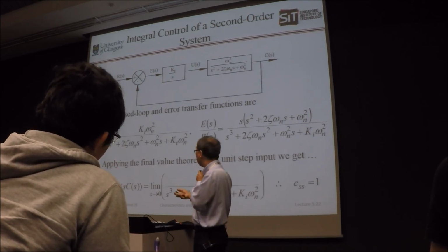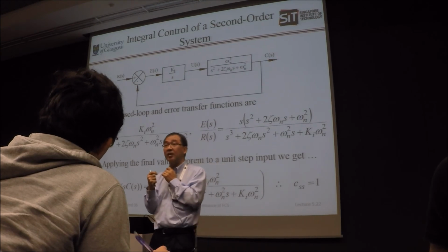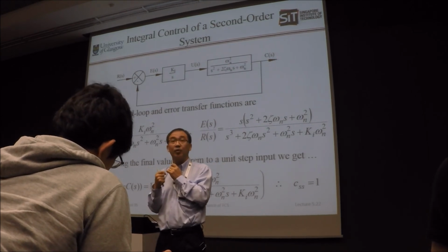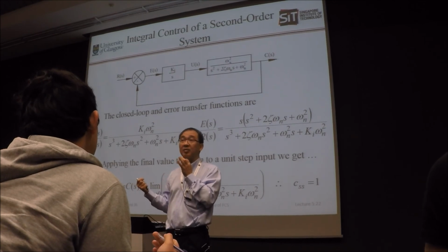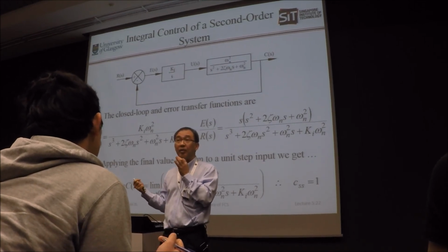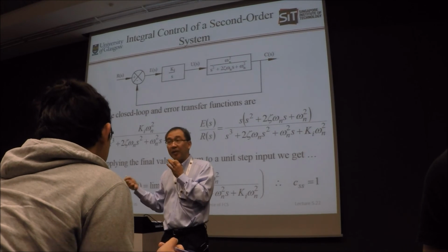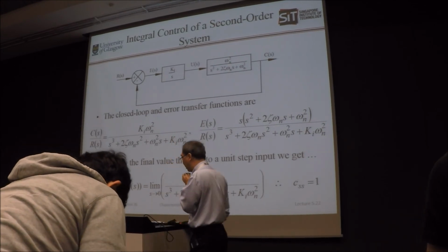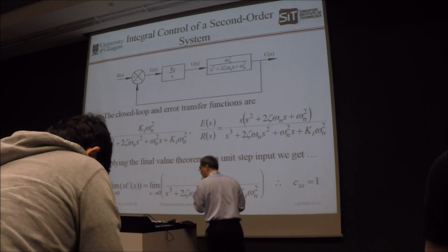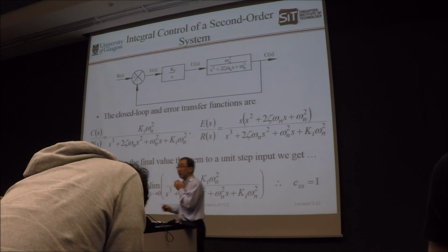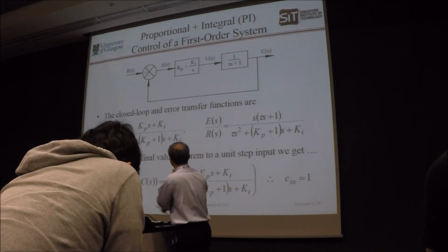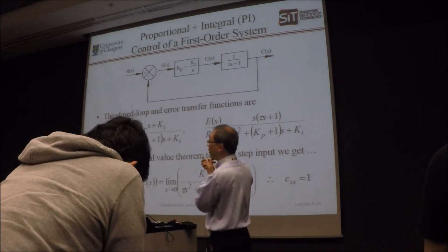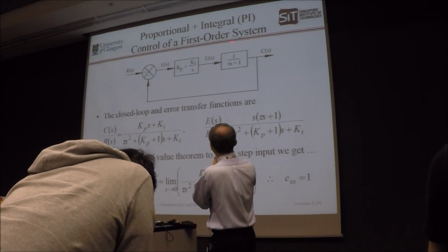In this case, under what circumstances do you end up with a situation where your closed loop system becomes unstable using your integral control? As much as we want to eliminate steady state error, we do realize that it can actually lead us to instability.